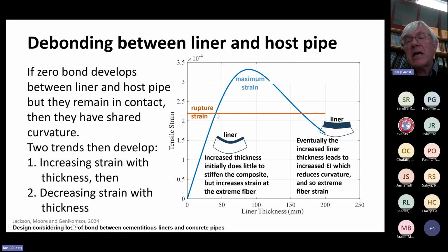And for some of these sprayed geopolymer sprays, there'll be a zone where we have unsafe design, where the actual strain demand will exceed the rupture strain of these sprayed materials. And since we're recommending that the design of these sprays be to prevent cracking of the spray, this zone would be a range of thicknesses that would be unacceptable for those sorts of products.